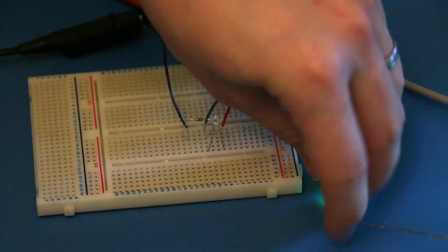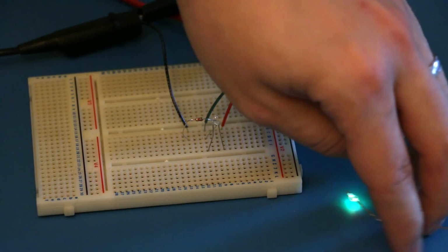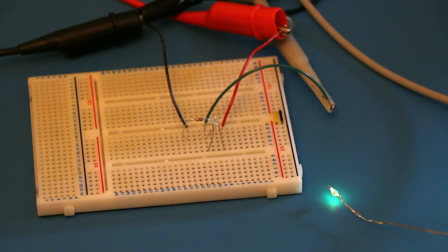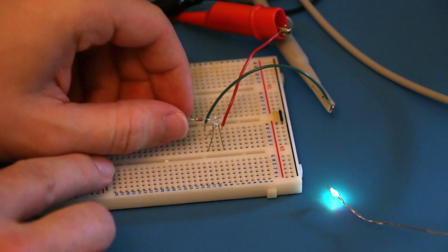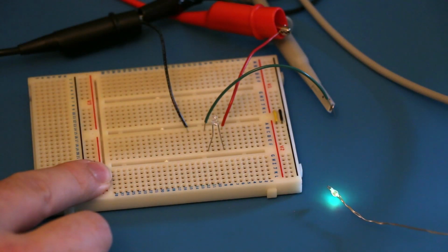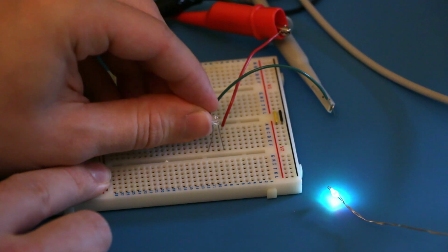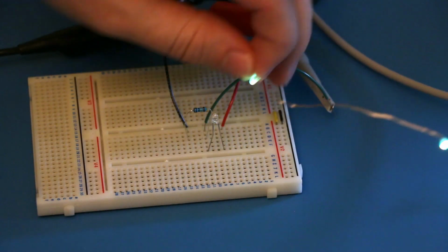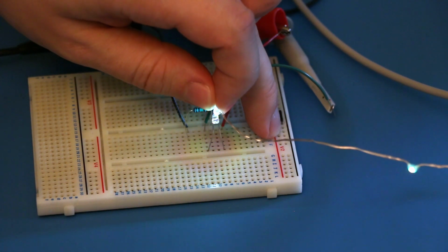Now, if I was to bring the chain close, then we don't have nearly enough sensitivity to see the output of the chain. I was originally using this very bright torch to try to test the signal, and it did see something, but it was a very small signal, about 40 millivolts or so. So what I did is I swapped out the 1 kilo ohm resistor for a 1 mega ohm resistor, and that provides a very, very big signal when using the bright torch. It's very easy to see, very clear. It also means that now when we use a much dimmer light source like the LED chain, we actually get a good signal out of it.